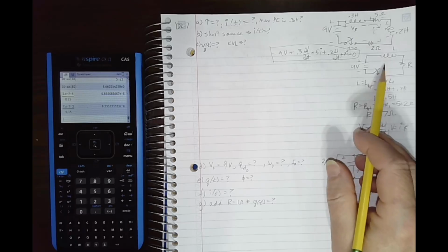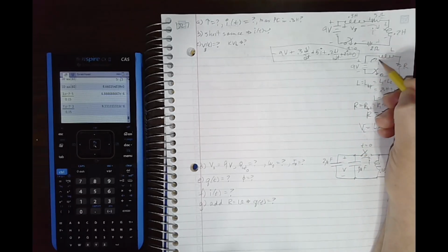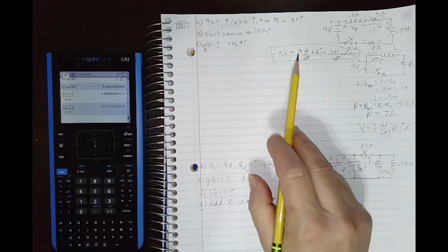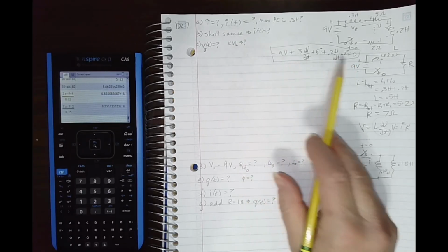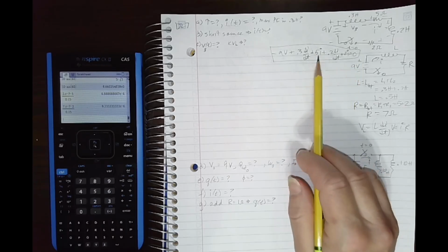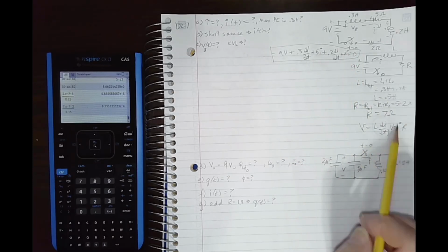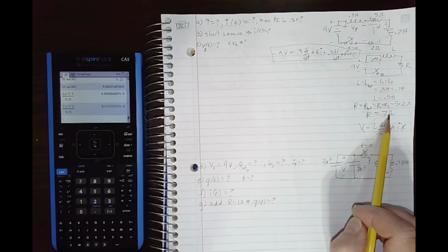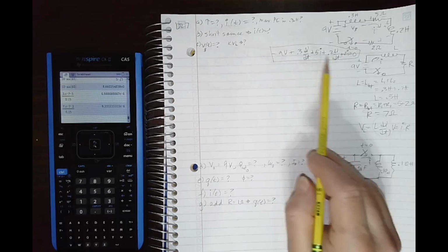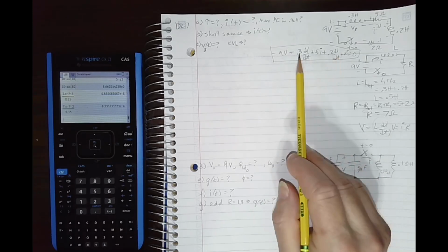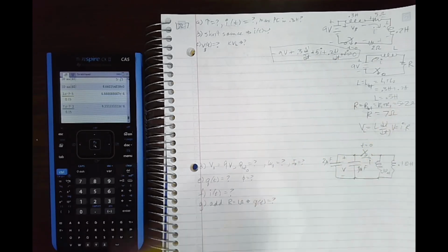We would get a similar equation if we do the same current for the small one. We would just have one L di/dt and one Ri, but you can see how adding resistors in series, we could just factor this out, we would get 7I. That's what we had for R total, 7, right? Same thing here, if we factor out the di/dt, we get the L combo is 0.3 plus 0.2. That's what we had there, right? So you can see that those two circuits have the same differential equation governing them, so they are basically the same circuit, right?